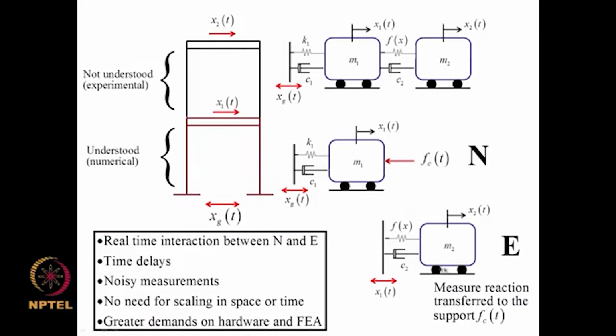analyzed in 30 seconds. That means the speed of integration and speed of testing must coincide. So this again leads to several complicating questions, and there are questions of time delays, noisy measurements, and issues like that which we need to take care of. So these hybrid testing methods are modern developments in earthquake engineering, and there actually the finite element modeling needs to shake hands with experimental tools, and there are lots of newer challenges that one has to face.